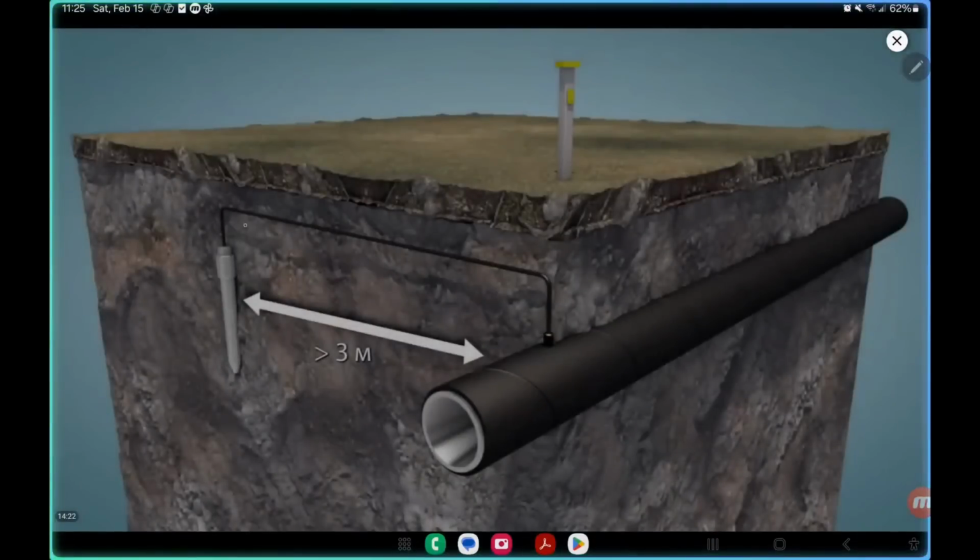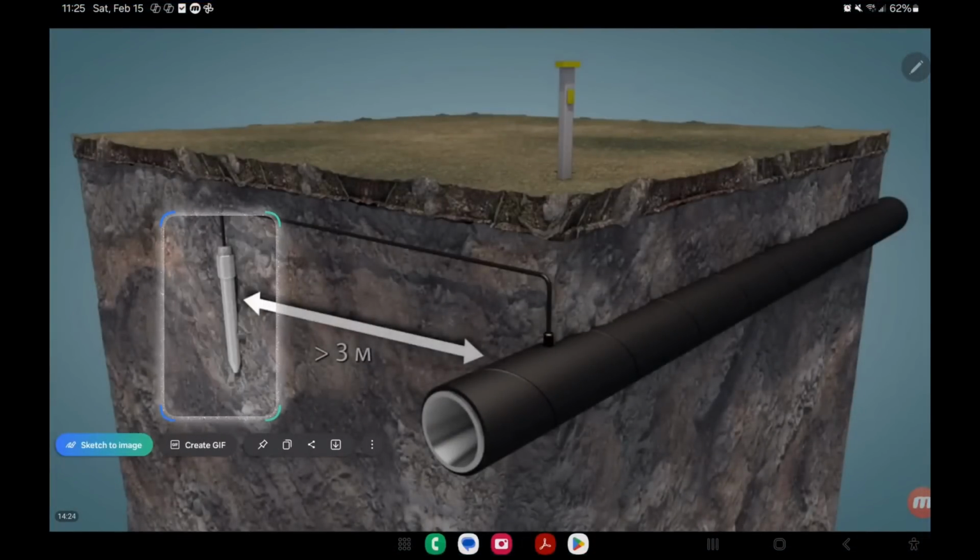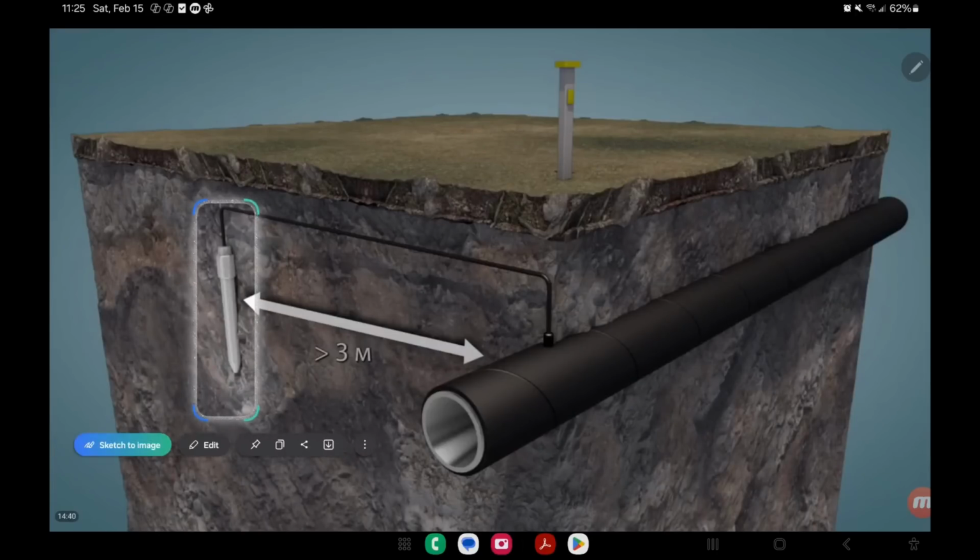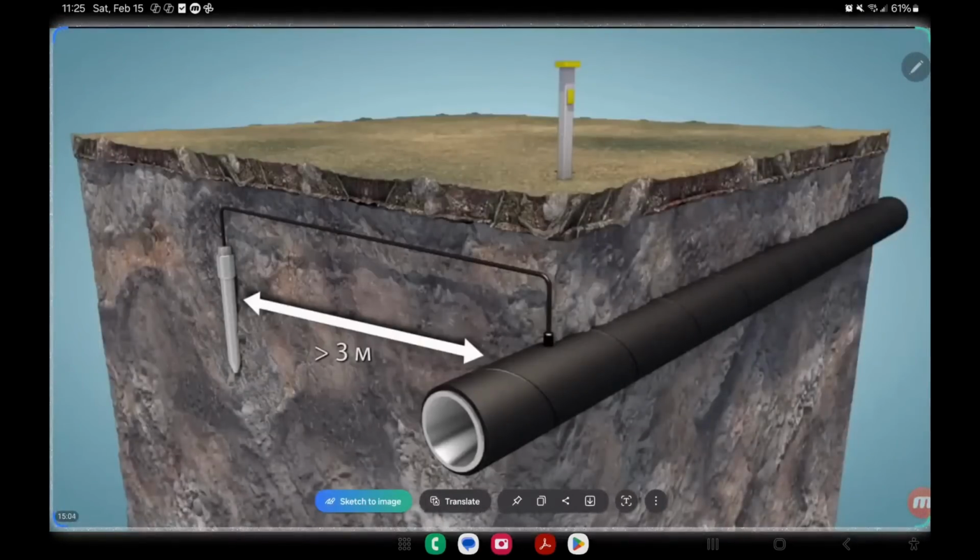It's the same thing that electricians also use. What happens is that electricians use copper bars, copper wire, they connect them to houses' electrical panels, but their grounding systems discharge through their copper wire bars and transfer to the bar that is on the pole that supplies the electrical voltage. There the electrical circuit is closed when there is a fault in the electrical panels. In our case, cathodic protection, our idea is that this anode sacrifices itself to protect the pipeline against corrosion.